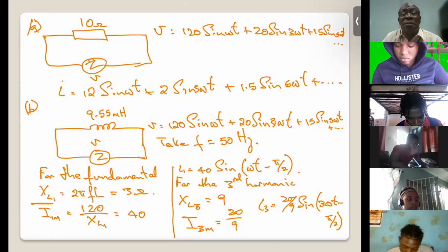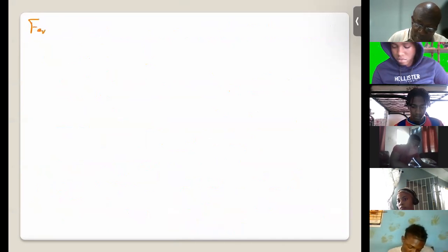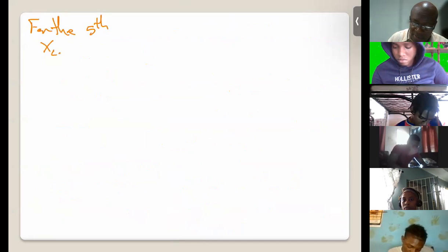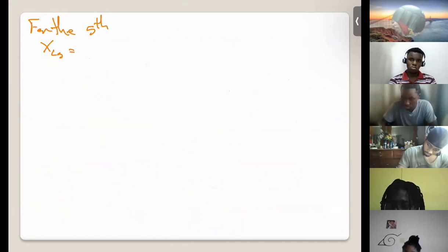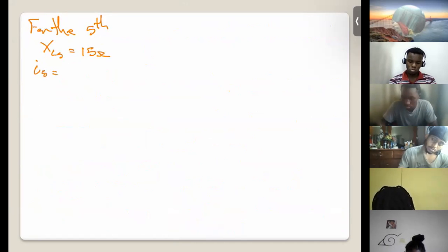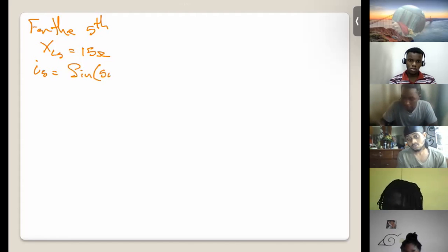All right. And then we go to the fifth harmonic. So the next step is for the fifth harmonic. XL5. Any volunteers? Do you realize how easy it is? 15 ohms. Which implies that I5 would be? Would that be 15/15 sine 5 omega t minus pi/2.